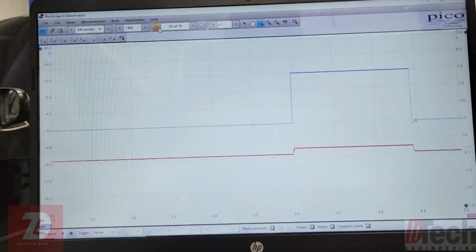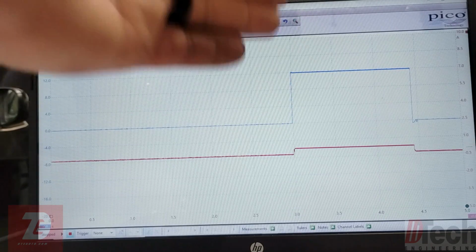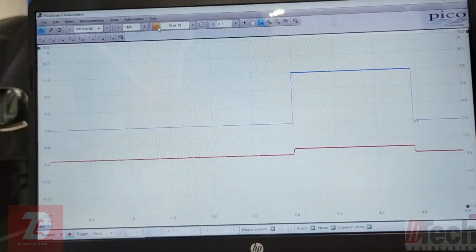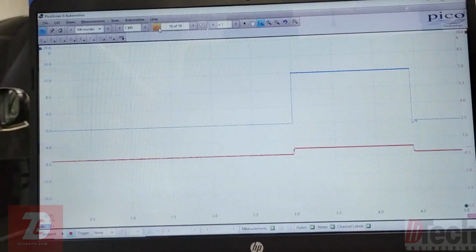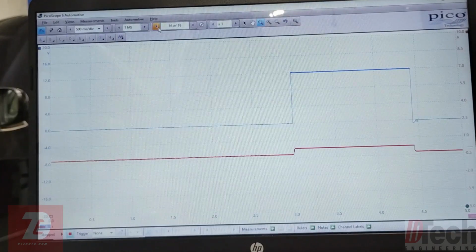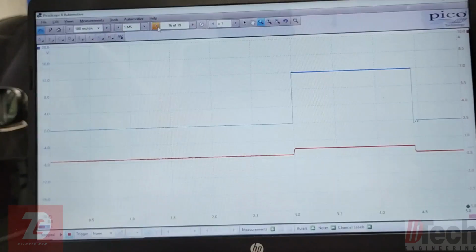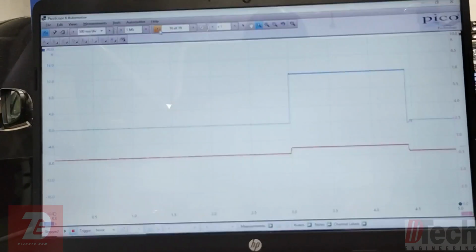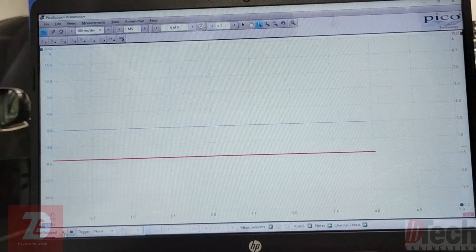So it's a protection mode, and that's where the trouble code is generated. Clearly here, it watches the amperage, nowhere near anything high, and so it's safe enough to hold it. It's at a normal operating level. So I just wanted to capture that and explain that to you guys. This is good enough. We have a fix.